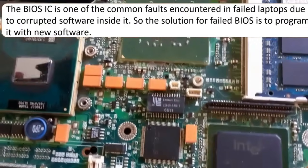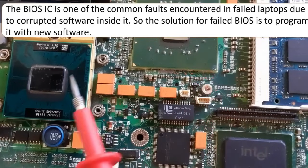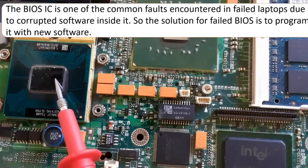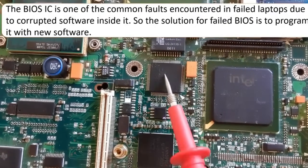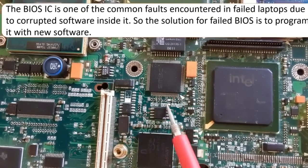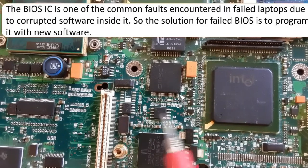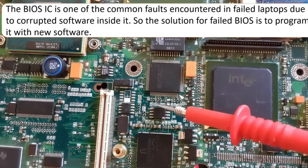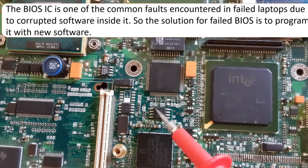Here we have the ICH, or the South bridge. Here we have the North bridge, and this is the processor: the processor, the North bridge, and the ICH. Here we have the SIO, or the Super Input Output. This is the BIOS. Here we have this white line and this hole, which means this is pin number 1, 2, 3, 4, 5, 6, 7, and 8. So it's always the same working principle.